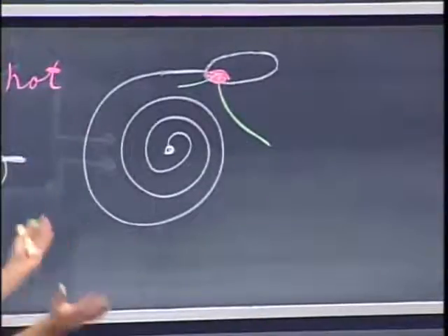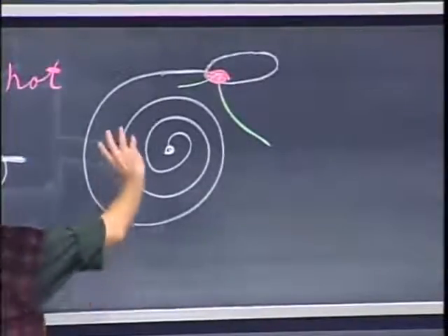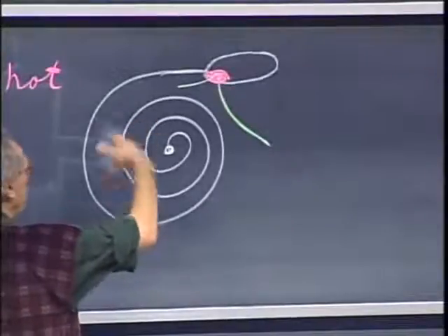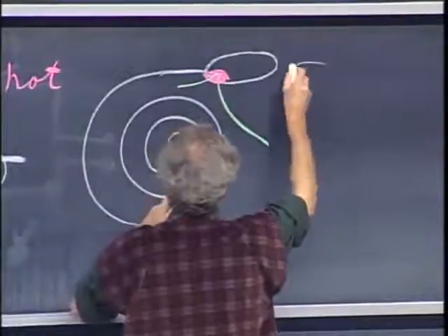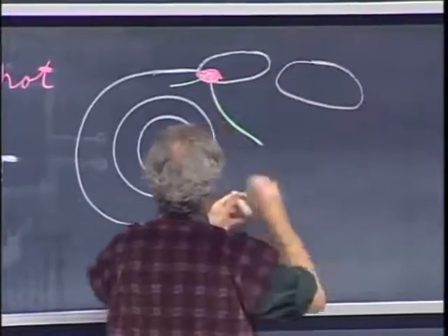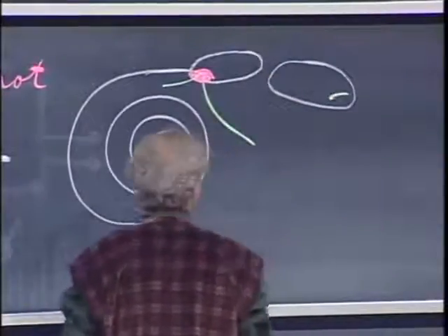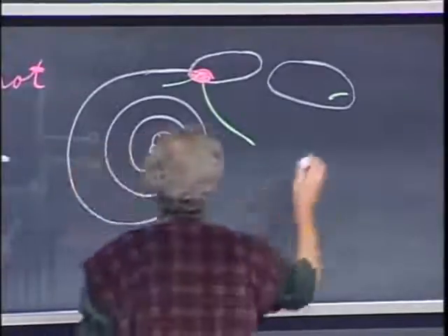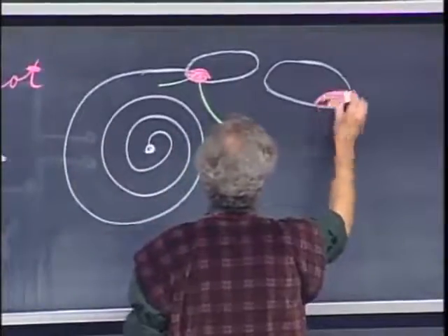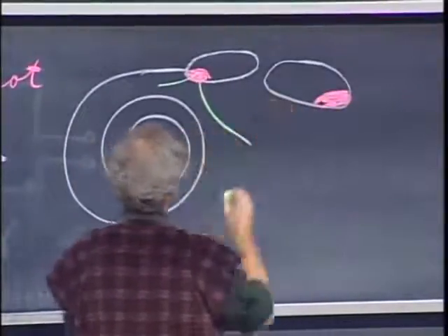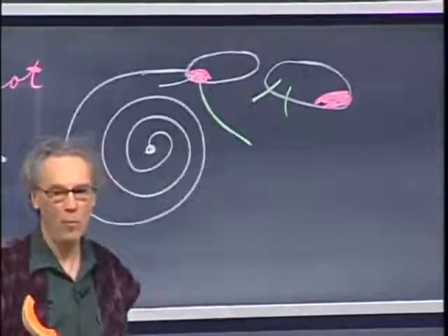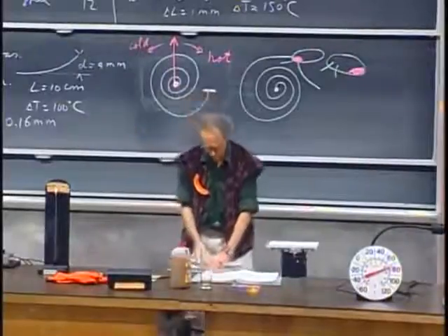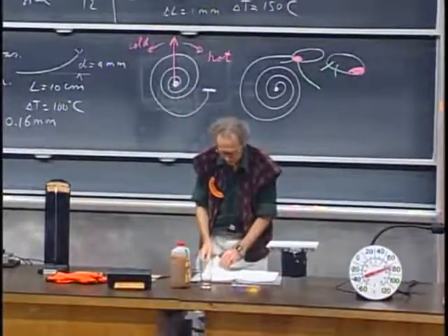Now the room gets warmer and warmer, and the bimetal will tighten up, will curl even more. And so there comes a time that this glass thing will tilt like this, and the mercury rolls out. And when the mercury rolls out, here's the mercury, these contacts here are open, and the heater will stop. And that's in almost every room. Very genius device.